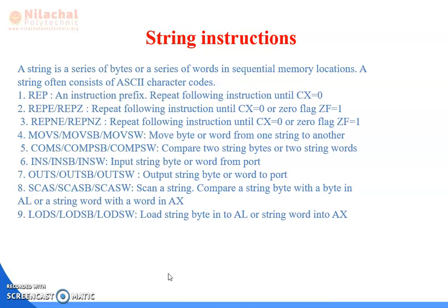Then INS or INSB or INSW, that means input string byte or word from port. Next OUTS or OUTSB or OUTSW, that means output string byte or word to port. Next SCAS or SCASB or SCASW, that means scan a string, compare a string byte with a byte in AL or a string word with a word in AX. Then LODS or LODSB or LODSW, that means load the string byte into AL or string word into AX.